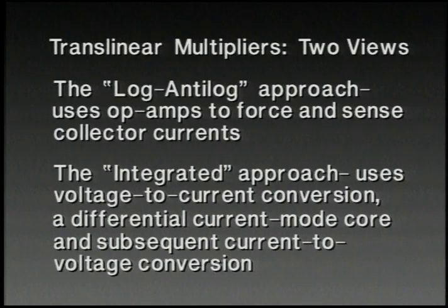A somewhat different view is what might be called the integrated approach, in which voltage to current conversion, using circuits which we won't discuss today, first converts an input voltage into a pair of differential currents, followed by a differential current mode core, and then subsequently another step of current to voltage conversion. Let's talk first about the log-antilog approach.